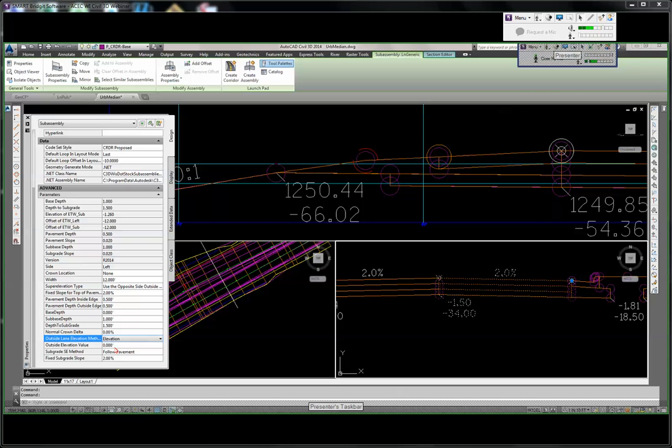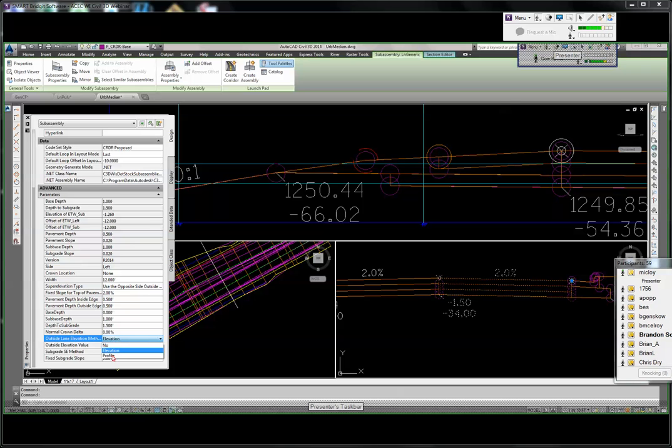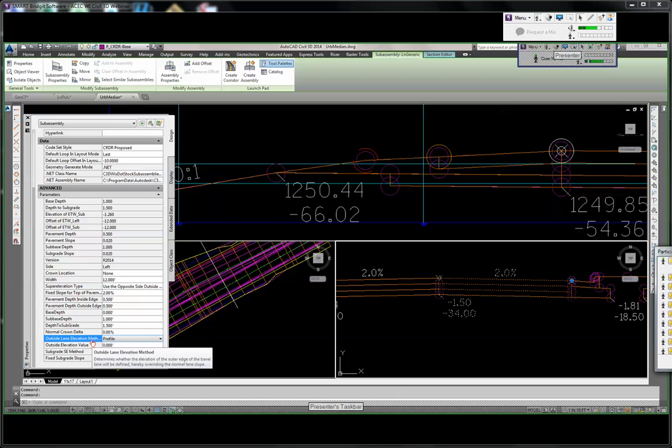Watch this because the default elevation is 0. It does not care that 0 is not realistic for a 1,200-foot elevation project. It's going to go down to 0 or try to. So make sure that you set in the elevation. Or if you set it to profile, that then turns on the option to target the profile that we have going on there.